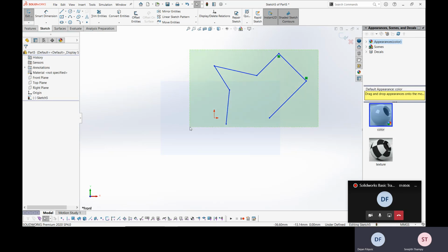And it doesn't mean that in SolidWorks you even need to start on a plane. You can have a 3D sketch as well. You can start anywhere on the 3D point. So just to explain what the consequence is: if you have a big assembly and you're introducing a small part, let's assume that when you made that small part, you did it like 100 meters away from the reference, right? When you bring it into the assembly, it will be put aligned with the coordinate system.